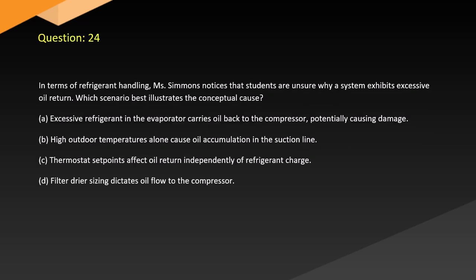Question 24. In terms of refrigerant handling, Ms. Simmons notices that students are unsure why the system exhibits excessive oil return. Which scenario best illustrates the conceptual cause? A. Excessive refrigerant in the evaporator carries oil back to the compressor, potentially causing damage. B. High outdoor temperatures alone cause oil accumulation in the suction line. C. Thermostat set points affect oil return independently of refrigerant charge. D. Filter dryer sizing dictates oil flow to the compressor.